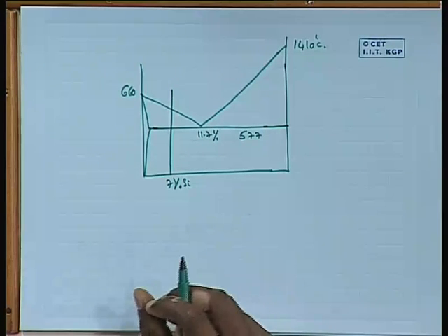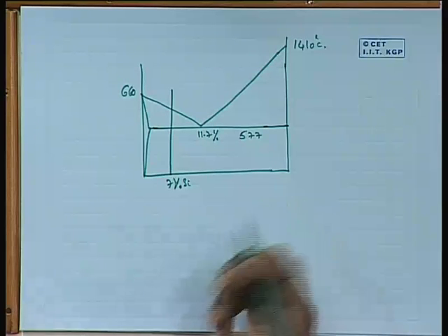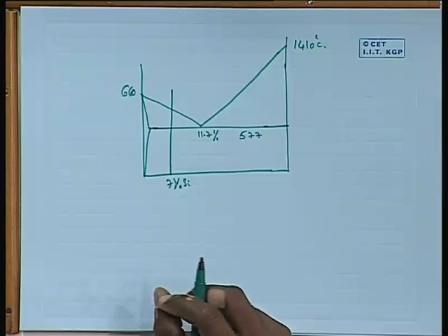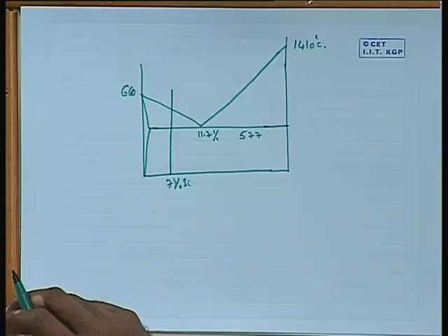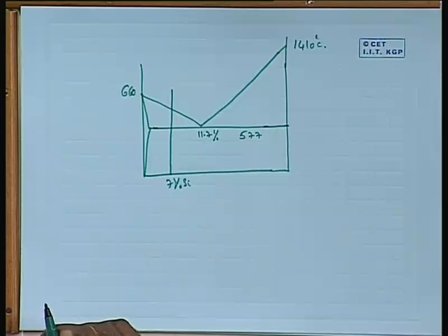So in these two cases, eutectic and hypoeutectic, silicon is usually in the eutectic mixture. That silicon in the eutectic mixture is usually in the needle form unless you do something. There are different ways of doing it. One way is to cool the alloy very rapidly.